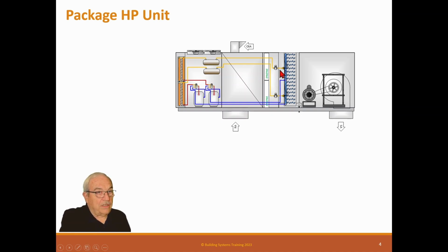So it's hot. It's not going through the evaporator. It's not going through the expansion valve. It goes around the expansion valve, as you'll learn in S1, and then it provides heating, and then the suction, which now is cold. It was hot, but now that it's down, it's a saturated vapor, and it goes back to the compressor, and that whole thing starts over again.